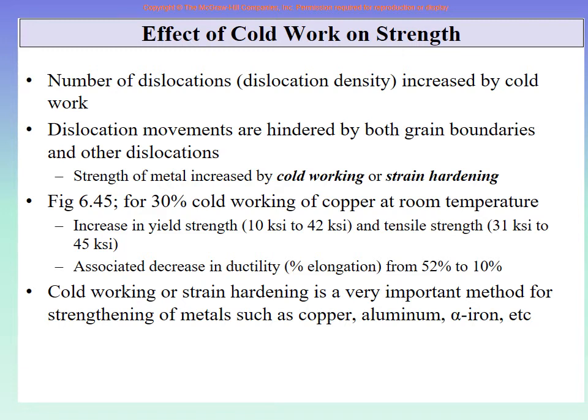And we know that grain boundaries resist deformation. So now if the size of the grain boundary has increased, this easy movement during deformation will decrease. And if there is another dislocation, that also will come and pile up on the grain boundary. So the size of the grain boundary will increase further.